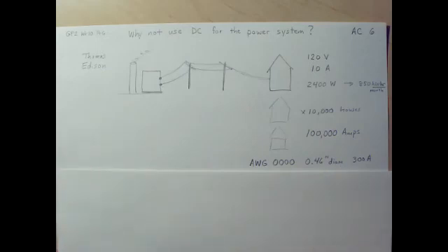You might think it would just be by the area, and it is sort of, except it's not that good. In other words, if you double the area, you don't get double the current. You get less than that, because the heat can't escape from the inner parts of the wire very well. So this is a terrible problem. This is not going to solve things.